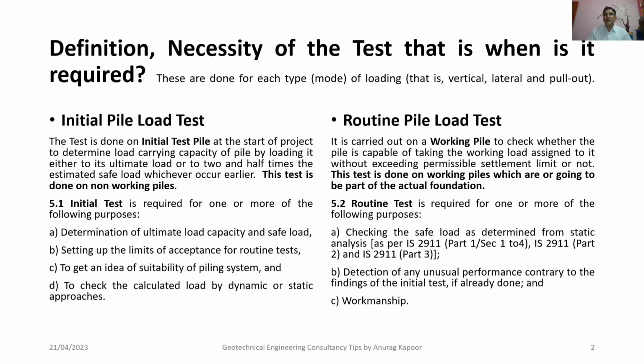Now, the routine pile load test. It is carried out on a working pile, which is part and parcel of the real-time foundation, to check whether the pile is capable of taking the working load assigned to it without exceeding the permissible settlement limit or not. If not, then the pile is assumed to have failed at the further design load. This test is done on working piles which are, or are going to be, part of the actual foundation.